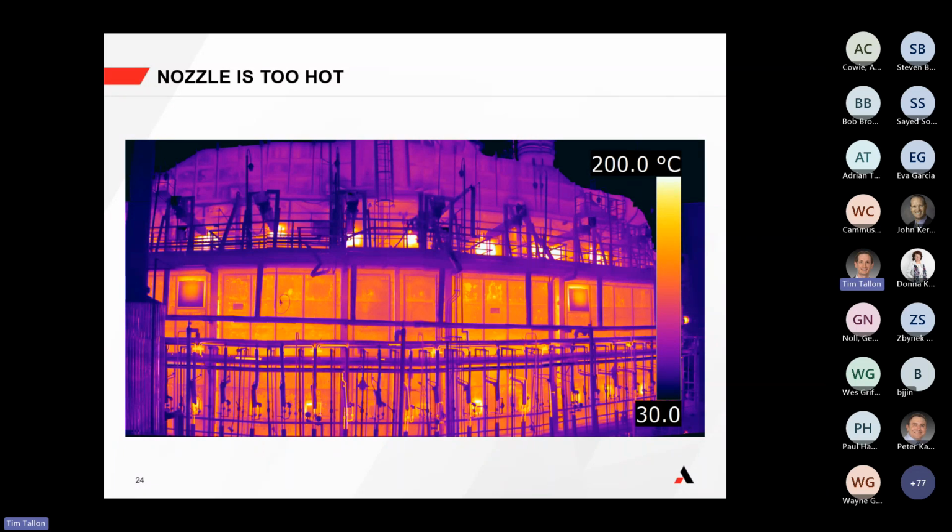Hey, Tim. It's also a safety concern. Sometimes the area is too hot for a technician to comfortably work in, and so the remote mount option provides a level of safety in that respect too. That's a good point. I've also heard examples where people's boots could burn up or start to melt because it was so hot in that area. So yeah, that's a good point, Joe. Between practicality of the electronics of the analyzer and also safety, it's definitely something to think about at certain locations.